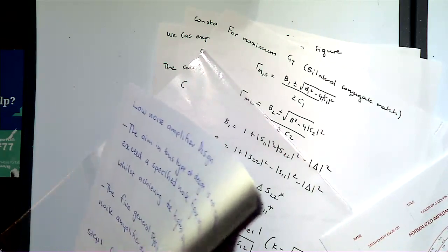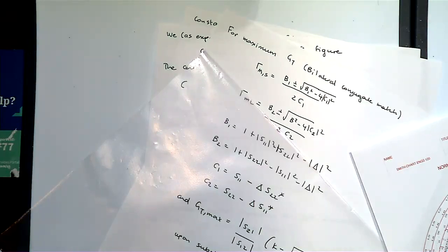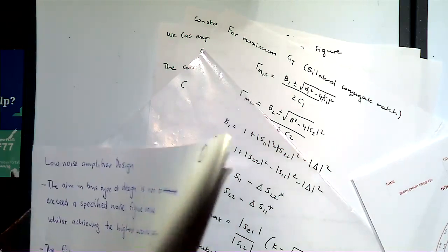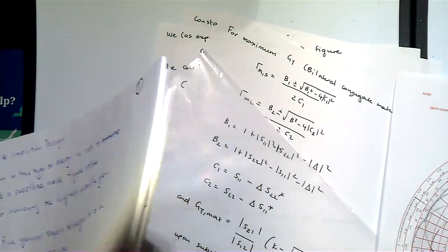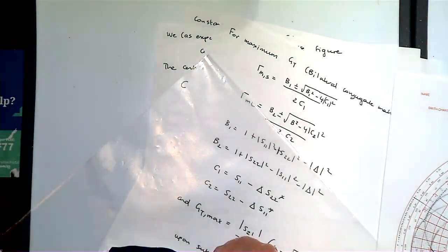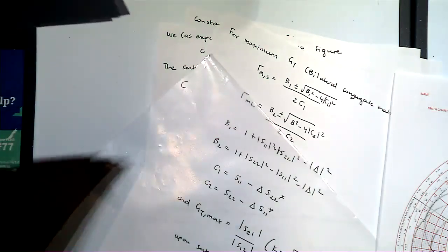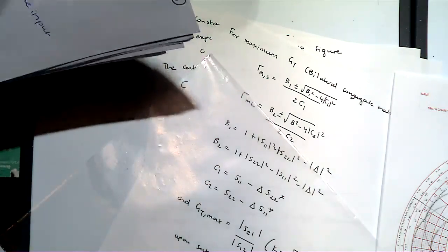I want it to look like this, so that I can achieve my noise. We should add this shunt, and then go back. Otherwise, if we want to do the match, we should go this way. Yeah, exactly. It's the opposite. Why is it opposite? Because usually what we try to do is match to 50 ohms. But here, what I'm saying is, I don't want to match. What I want to do is work out the impedance that gives us the desired noise figure. So I'm doing the opposite now.